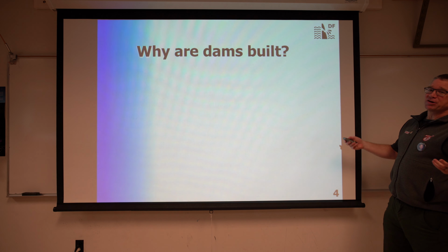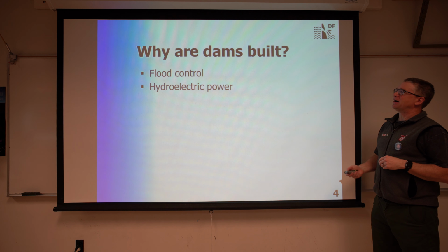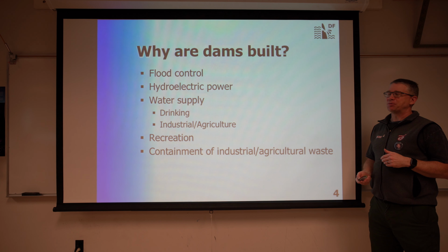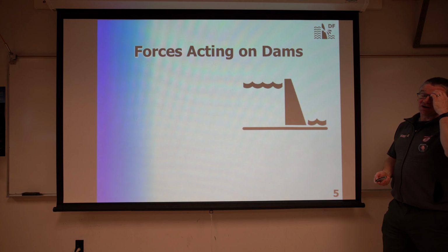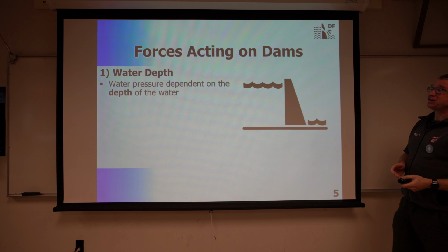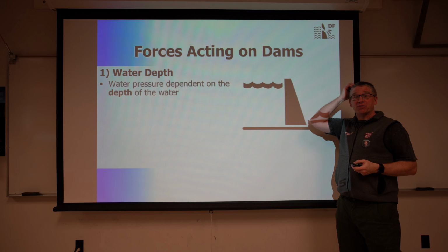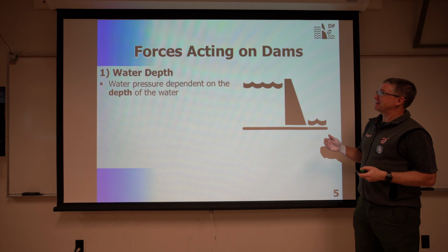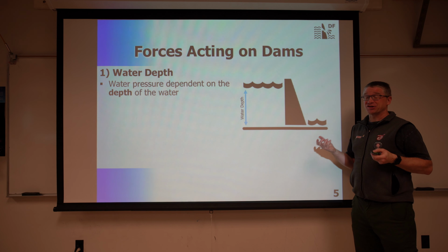All right, why dams are built, pretty straightforward. Again, a variety of reasons here. I'll kind of skip over this. What I want to look at are the forces acting on a dam. The most important thing is the water depth. The depth of the water really dictates the amount of pressure that it exerts on the dam.